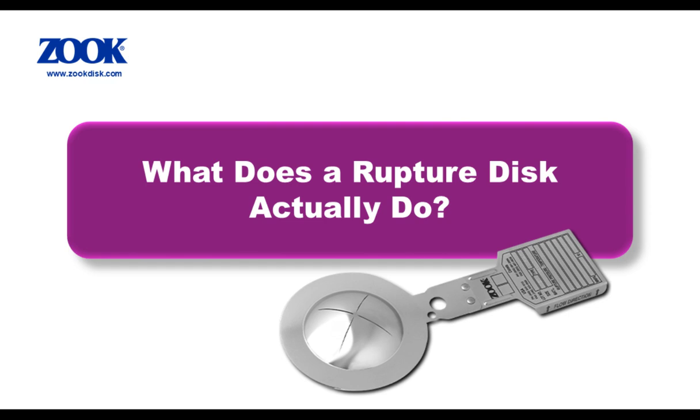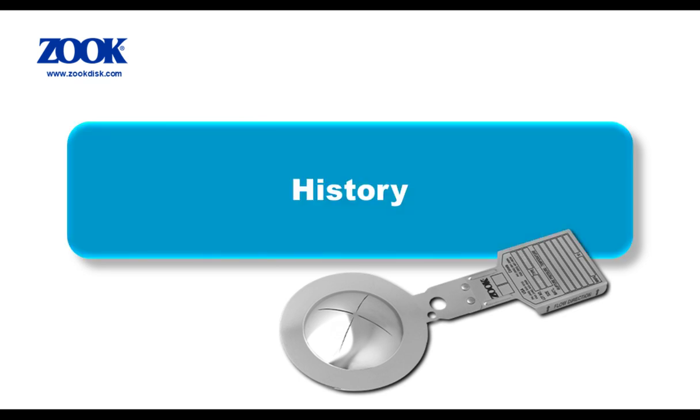Rupture discs have been around for a long time and have earned an excellent reputation for successfully protecting all types of pressurized equipment. The original rupture disc was simply a piece of thin metal foil clamped between pipe flanges, designed to be the weak point in the system. As the internal pressure increases, the foil yields because it is thinner and therefore weaker than the vessel wall, eventually failing to safely relieve the overpressure and protect the integrity of the system. It was a simple design but very effective.